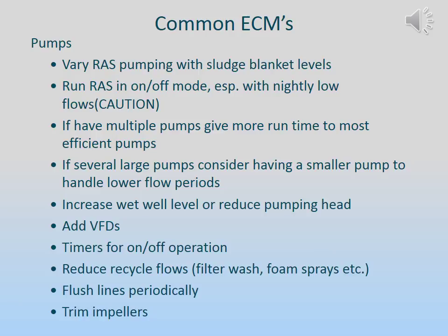Use timers for on and off operations. Reduce recycle flows such as filter backwash, foam sprays, etc. Flush the lines periodically to remove any accumulations that could be creating head in the lines and trim the impellers.